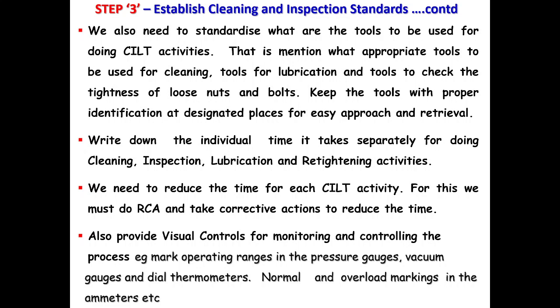Write down separately the time taken for doing cleaning, inspection, lubrication and retightening activities. We need to reduce the time for each CILT activity. For this, we must do RCA and take corrective actions to reduce the time.